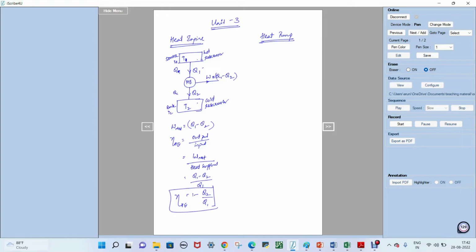And now we have the heat pump. This is basically sending heat from a low temperature source to a high temperature source, or rather from a cold reservoir to a hot reservoir, while using some work. Let me call the engine's output the work of an engine, and this the work supplied to the pump. This is called a heat pump. It is drawing heat from the cold reservoir and pumping it to the hot reservoir. It's a reverse of what is happening; everything is reverse.